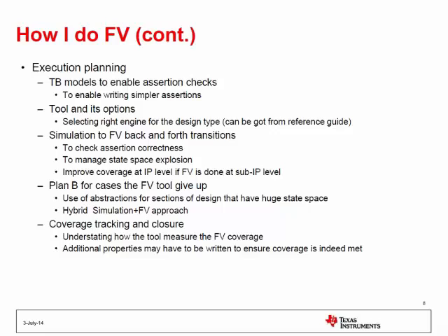And having additional cover properties, I think the other two speakers spoke about. Where I found it effective is, first, something very straightforward. If it is a complete combo logic, the tool can easily handle it, and all you need to do is have a very good set of assertions. An example I have given is the pin multiplexing logic. Usually in the SoC, you will have multiple I/O pads, and you will have a huge amount of multiplexing happening between your various IPs. So this is a very useful way because you will see a lot more automation you can do.